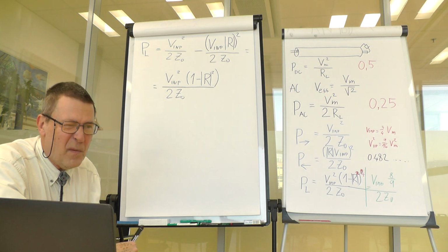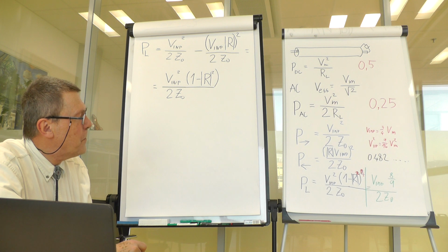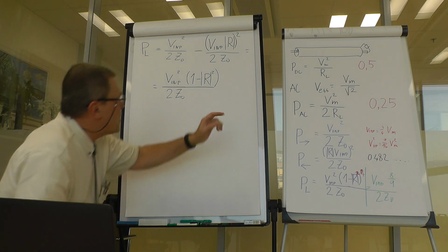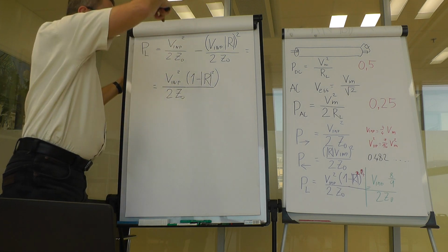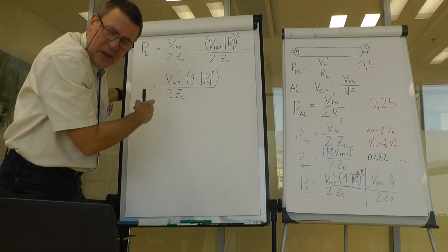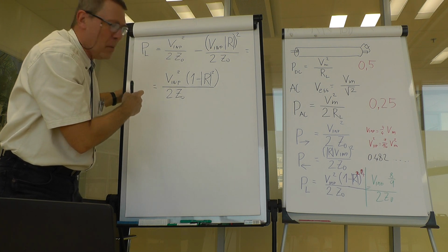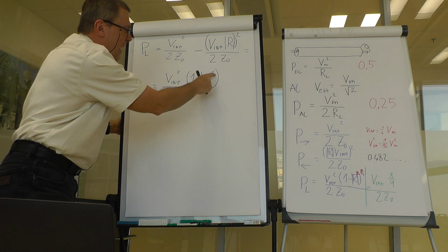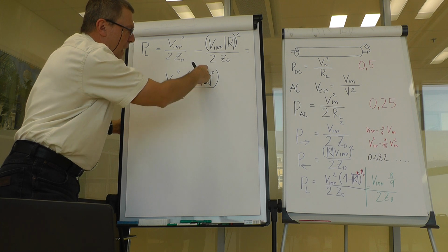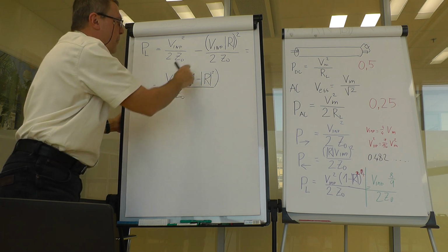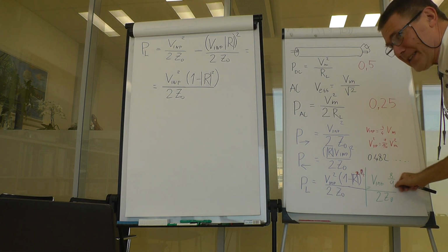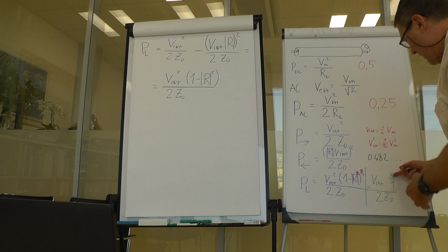Yes, thank you. And also, the last part there, this V, after this equation. After this, what I have done. So the reflection coefficient has been identified as far as I remember, 1/3. When I raise it to second power, I get 1/9, and if I subtract that from 1, I get 8/9. Okay, yeah, I got it's 8/9.